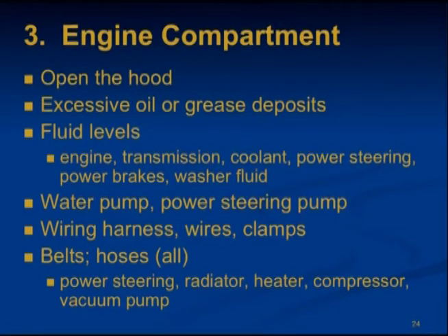Windshield washer solvent is full, and check that for leaks also. Check the water pump, power steering pump, and power steering hose. Make sure that they're mounted securely with no leaks. Hoses shouldn't be cracked or leaking, and the clamps must be secure. Check the wiring harnesses. Look where the wiring insulation may be rubbing through because of engine vibration. Make sure that all clamps are secure.